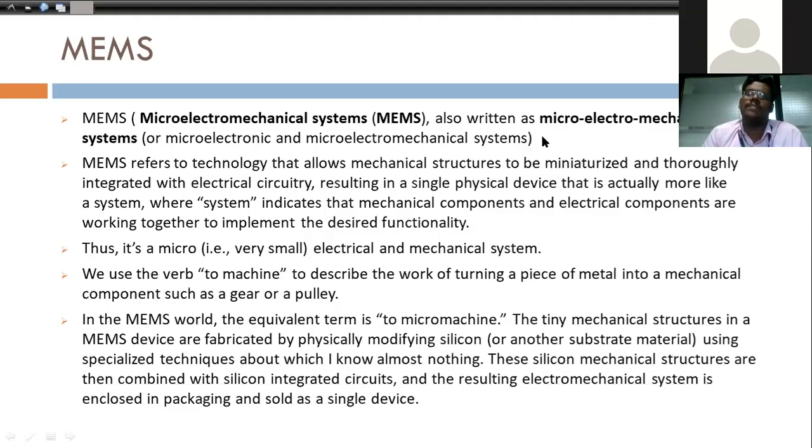Security issues depend on the protocols. What protocols did you use? We faced many issues, and those are the major ones. For security, we used the MQTT protocol mainly over WebSockets. WebSocket is secured, and we have a particular WebSocket port for accessing it. Based on the WebSocket, we used the MQTT protocol. But if you use MQTT on other ports, it is an open port, so whichever person is able to hack can take the data.